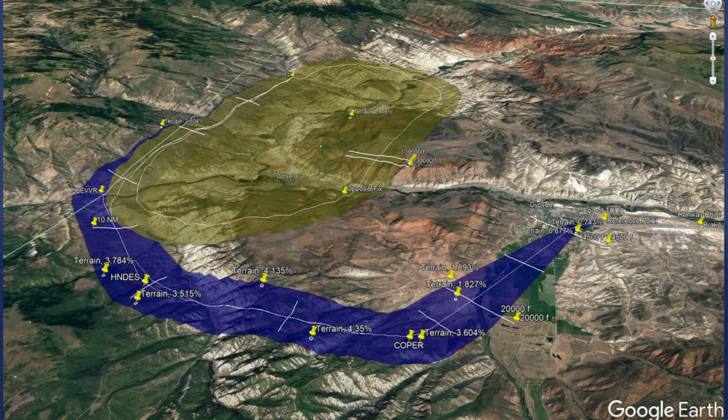So this procedure is designed to be flown at V2 and then enter holding once you get to your holding fix, and you're going to hold with right turns. So what we're looking at when we design this is, like I said, flyability, but also where are the obstacles and what's the best place for the aircraft to be flying, as compared to TERPs or as compared to the published procedure.